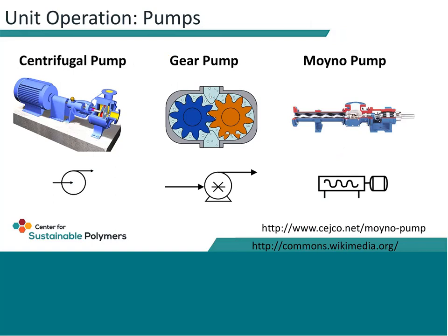So there are many other ancillary devices. Pumps are a big part of these types of facilities, and they come in many different types. There are hundreds of types and many different brands, and I'll just show you 3 very different types. This is a centrifugal pump you see over here on the right. You have a spinning head here, which imparts fluid head through velocity, which then converts to pressure coming out of the volute right here.